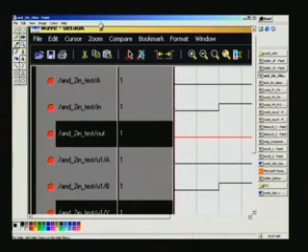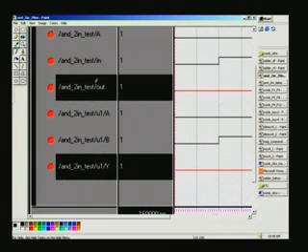So again, this is basically from the wave which we have seen after invoking ModelSim, and we will also invoke it once again. It has been pasted in Paint, and that's why you can see the readability is far enhanced now. So you see that A and in are the two, I hope you can read this on the TV monitor. A and in are the 2 inputs of the test bench, and out is the final output. And this corresponds to the A and B inputs of the design, and the Y output corresponds to the out.